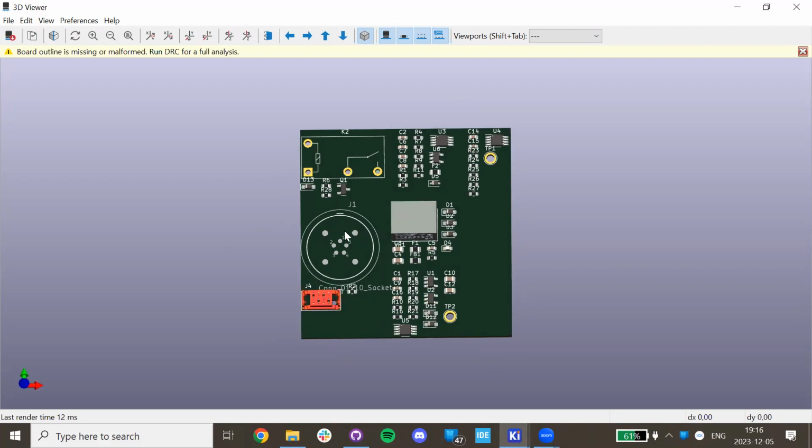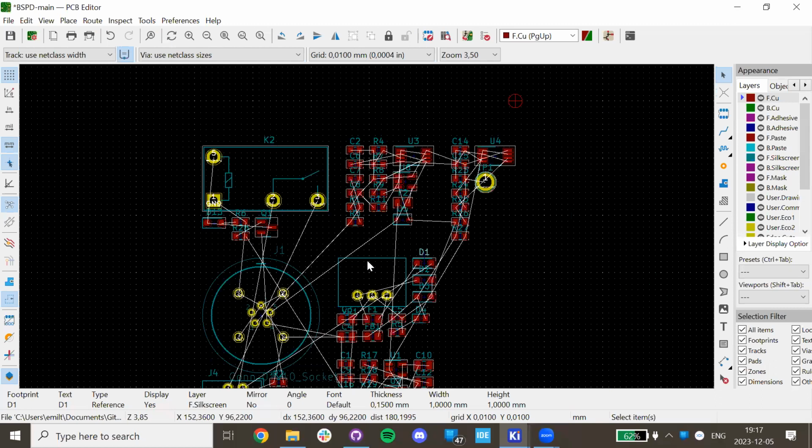So that means for me, I usually go about routing around the connectors, because usually your connectors need to point in some way, or I think if you look in the rear LV box, you can see quite well how we try to align connectors to other PCBs and such. So I would usually start with just those.